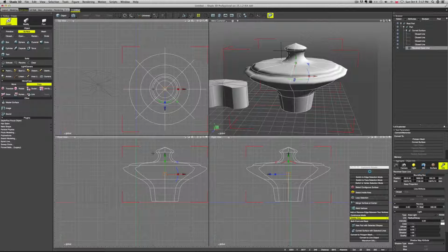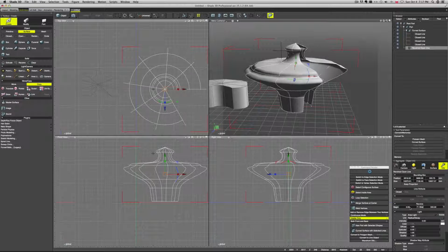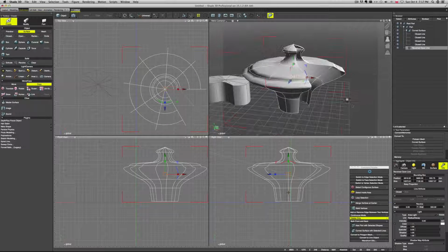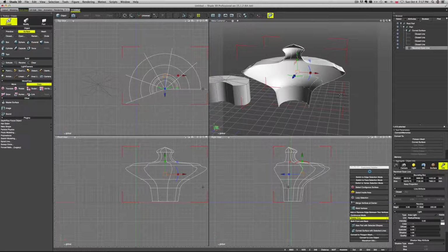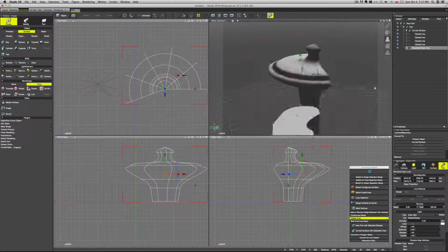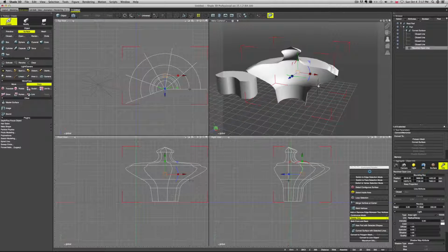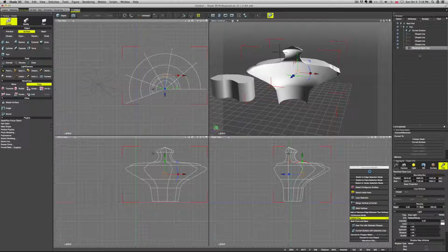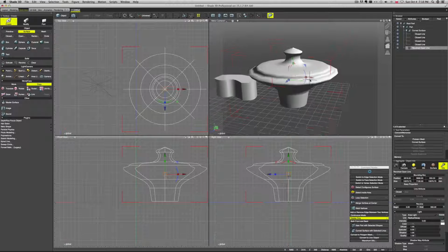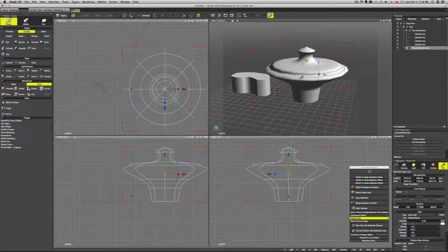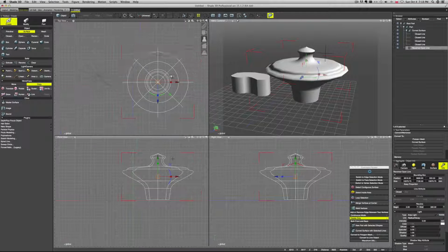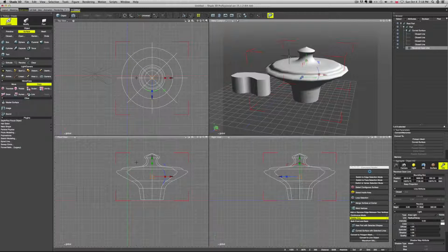And you can see here in our info tab we have begin and end as a full circle, so to speak, 360 degrees, and we can change it if we don't want it to be revolved completely, fully 360. We can put a different angle. We can put 200, for instance, and we can go back to the full circle. So this is another way we can create a number of objects using the revolve option.